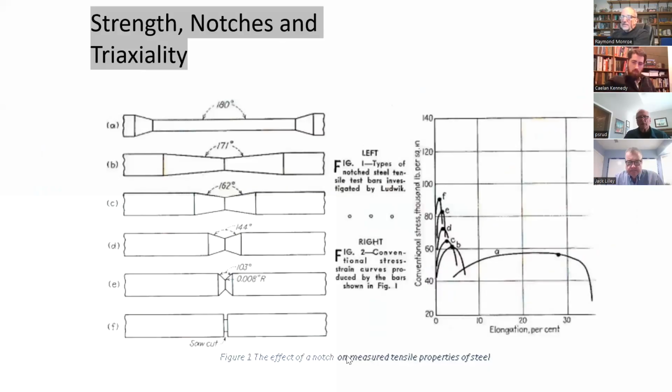Well, can we go back to that very first slide? This slide, yes. So you were talking about the best design for a test bar would be one that has no taper and no notch. Okay. But ASTM allows some taper in the test bar so that you assure that it breaks in the middle between your two points. So I guess my question is, how much taper can I have before I get in trouble? You know, Paul, that is a great question.